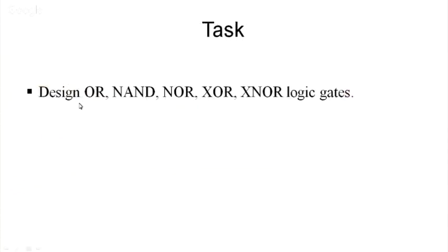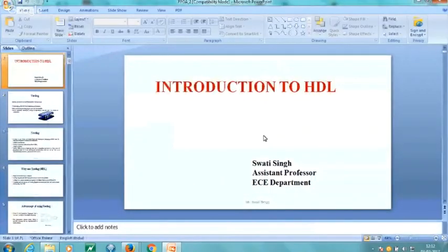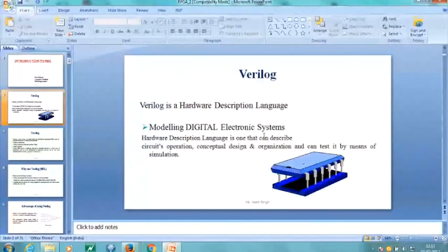In a similar way, you can design any of the AND, NOR, or XOR gates. So it is a basic example of how we simulate and implement our Verilog program on Xilinx: write the program, simulate it, and then implement it. But from a research point of view, first of all, we need knowledge of Verilog programming. So now, an introduction to HDL. I'm going to discuss some small projects and then research work.